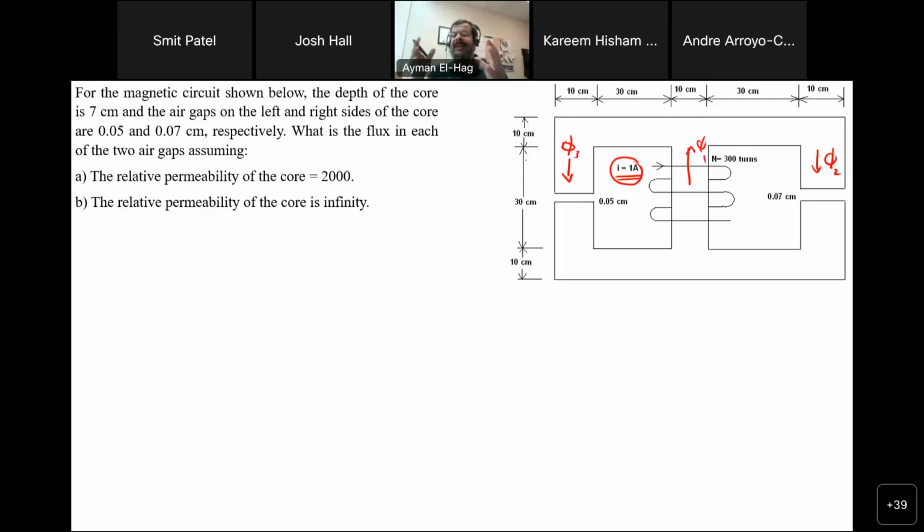And we know that the magnetic circuit somehow behaves like an electric circuit, and the flux specifically behaves like the current. So you have a flux going through a branch, and the flux here is the same as the flux there. It's the same flux. But then it will see a junction, or a node, or two different paths. So then the flux will be split. Flux to the right, we call phi 2, and flux to the left, we call phi 3.